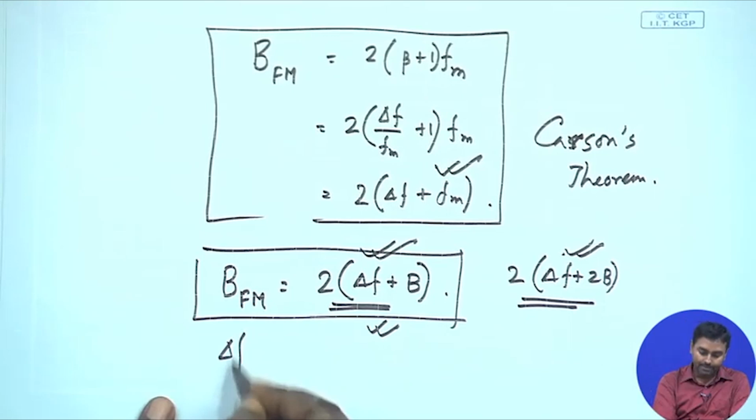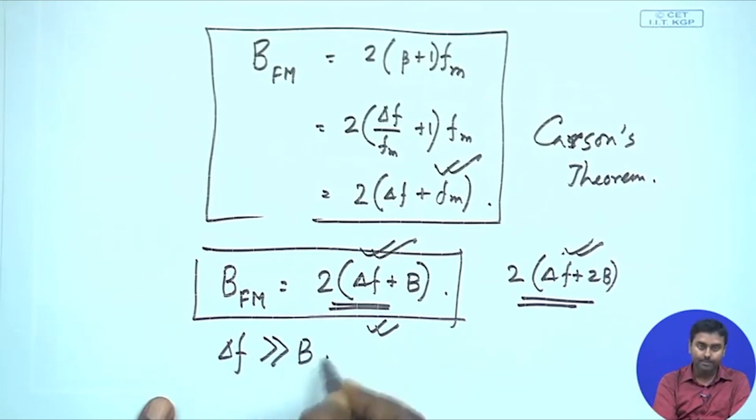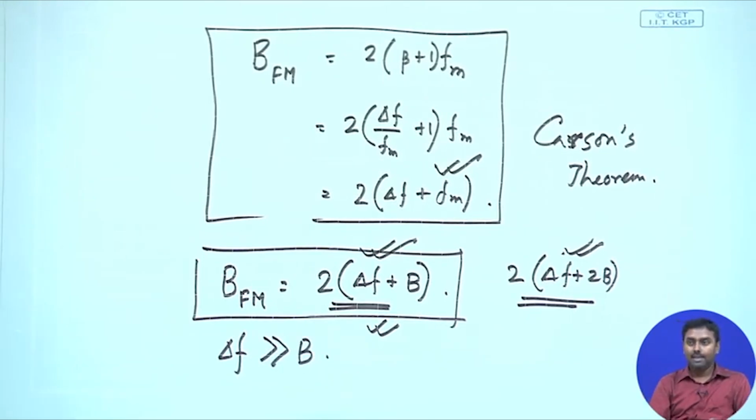If my del f becomes much bigger than b, then what people were actually saying, that the frequency deviation should be the FM bandwidth, actually happens. There del f is already large, it is not the narrowband part, it is the wideband part, where you have a huge deviation, that means the kf value is already big.